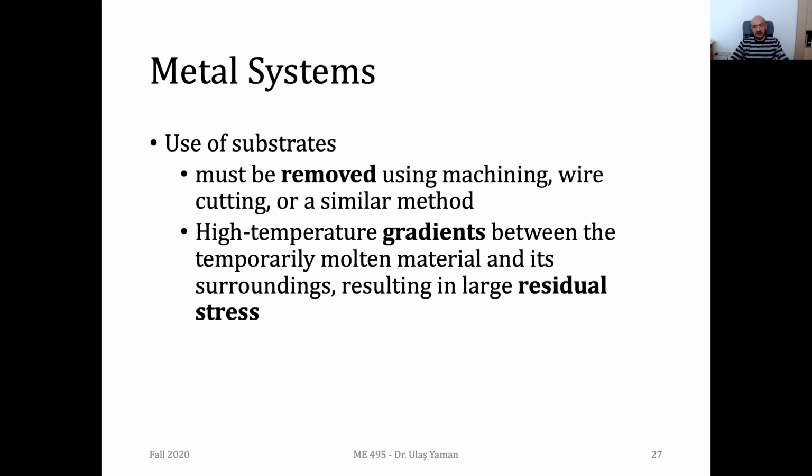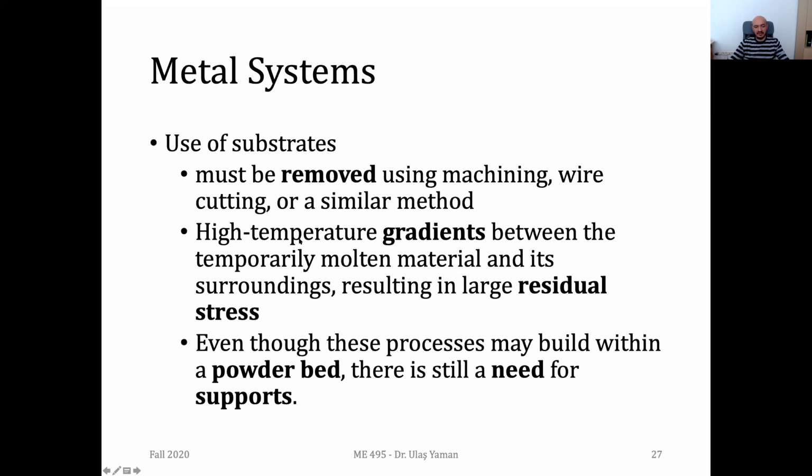In other cases, you may have more temperature gradients and there might be warpage, some residual stresses remaining around. You need to be aware of them and, as I said, spend time on having better products, and you can do it by adjusting the parameters. So you need to spend more time on the 3rd and the 4th steps. And in some cases, you may do all these steps and still cannot get a high quality product. If that's the case, you should start from scratch. Modify your design and modify the parameters, so it will take more time on the metal systems to get a high quality product.